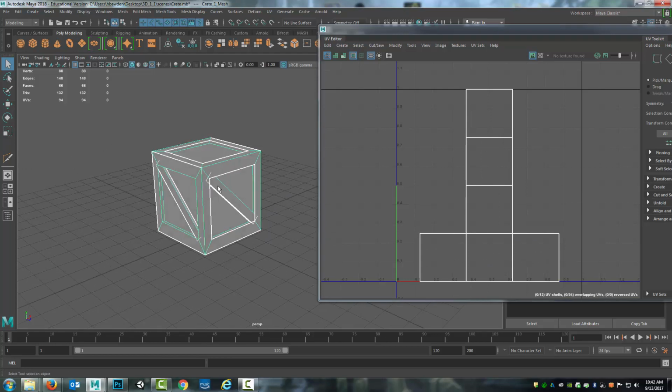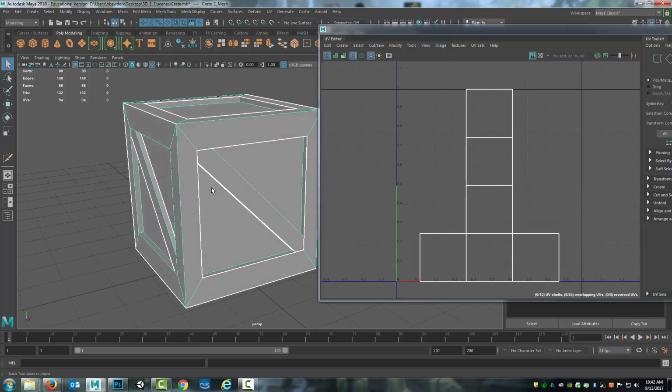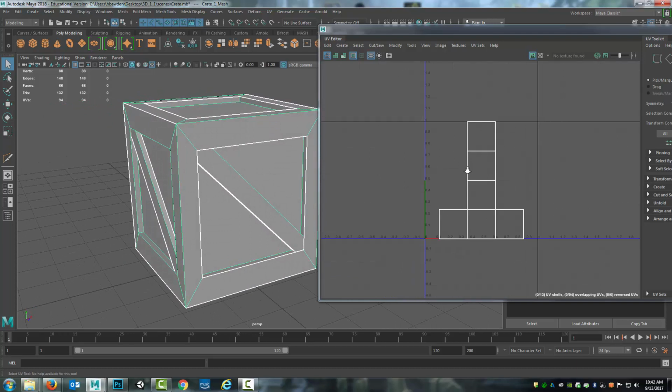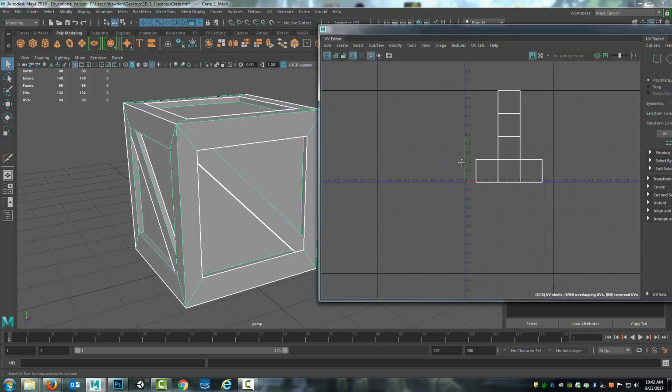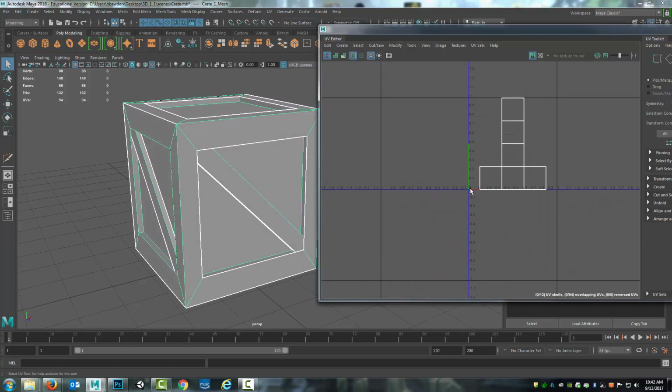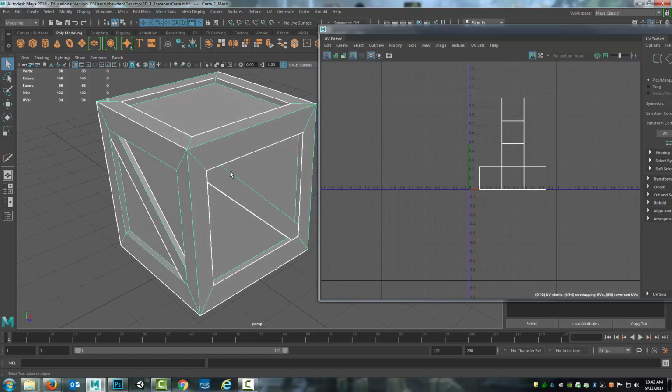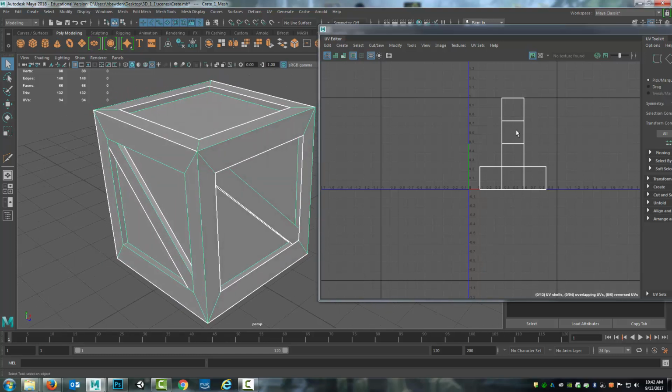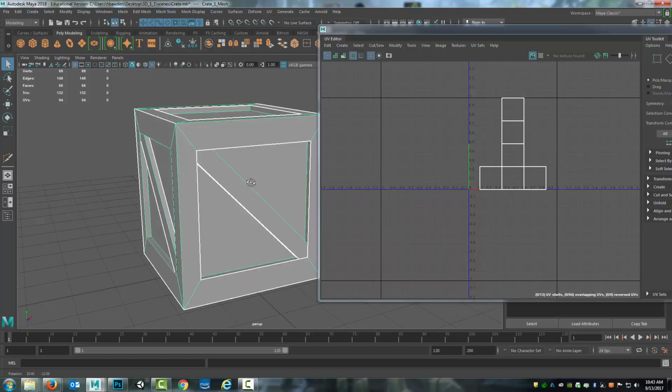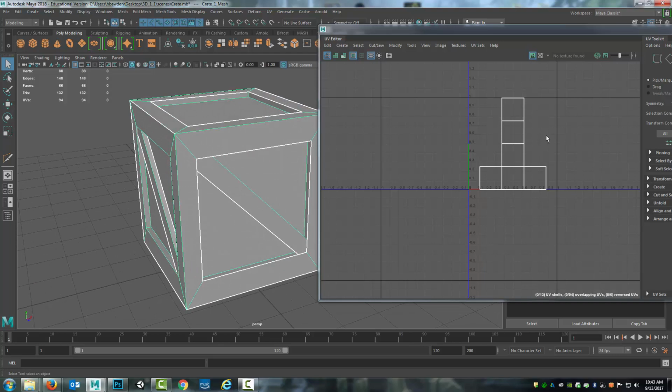When you're doing UV mapping, especially for objects that are going to have a custom space, this is where I'm going to start talking about 0 to 1. Once again, the 0 to 1 area is from 0 to +1 and from 0 to +1. So in this square, if you want a unique texture, you're going to want to fit everything in that square. There are things called tileable textures where the texture will repeat itself and continue on, where the UVs would actually go out of that 0 to 1 area. But for right now, focus on doing your UV mapping in the 0 to 1 area.